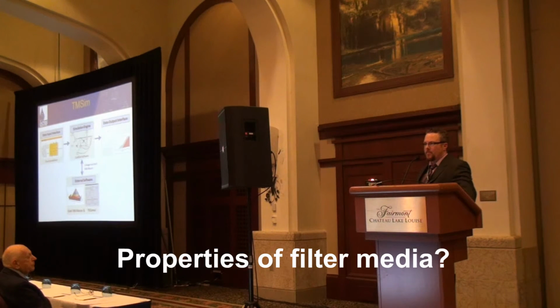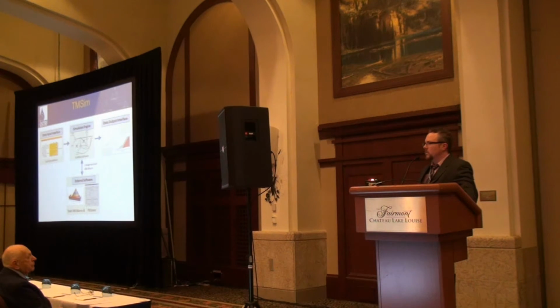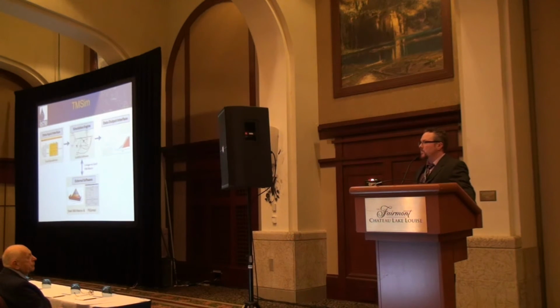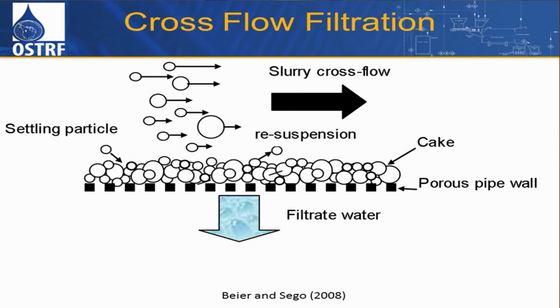Yeah. So in the lab, we started off with just water well screen, 2-inch slotted pipe, with up to 200 micron slots. So the standard monitoring well you'd use for geotechnical well slots. That's what we started with. And nothing else on top? Nope, just the pipe. And then the coarse fraction bridges across those openings, and it's actually the tailings themselves that are doing the filtering. That pipe is just there to support a structure for the sand particles and the cake.